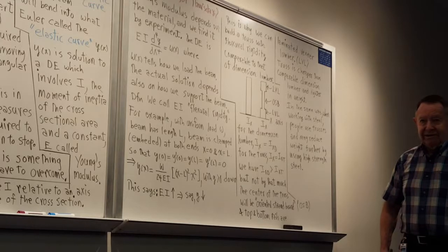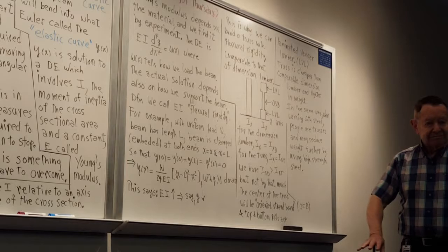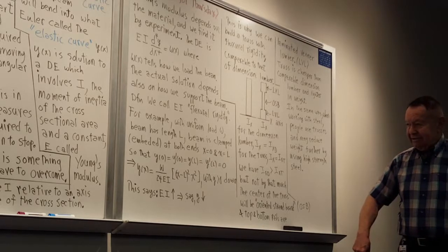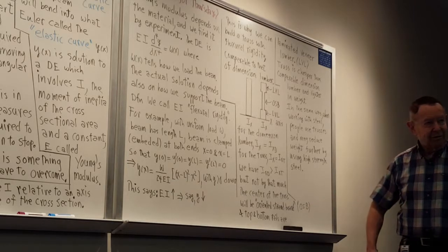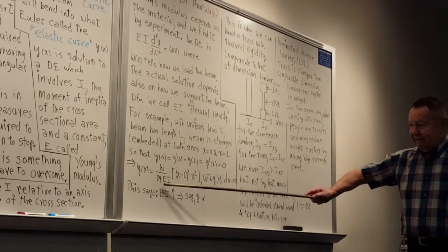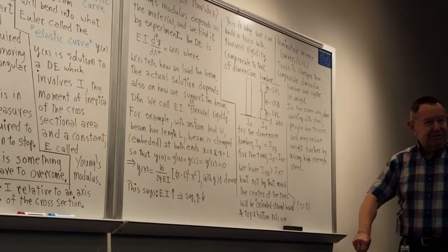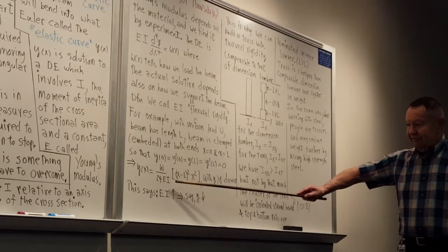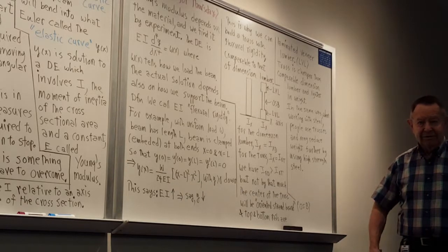So the strength then, in terms of reducing how much the support sags under load, is proportional to what is your moment of inertia. Your E depends on what the material is, and if you're using that kind of material, that's what you're stuck with. But what you can vary is your moment of inertia, depending on what choice you make.